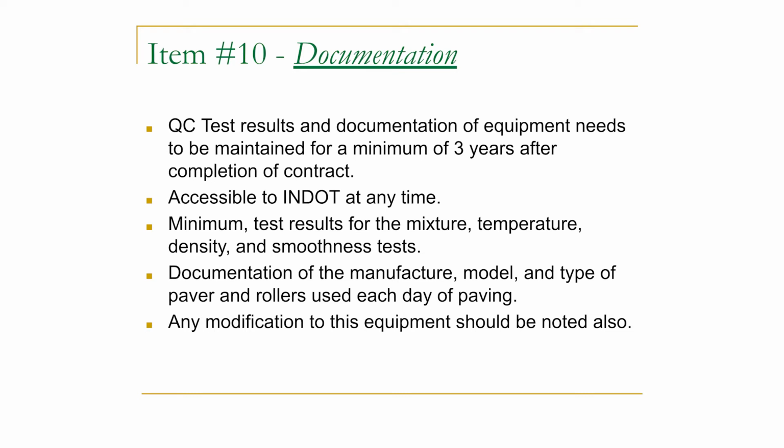You just have to keep the records on file for 3 years, according to ITM 803. They must be accessible to INDOT anytime, so they have the right to come in anytime to look at your QC plan. Minimum test results for mixture, temperature, density, and smoothness tests are all test results you keep on file as well for 3 years.